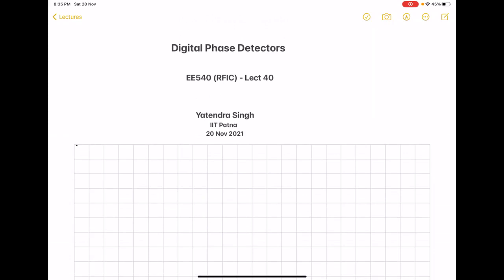In the previous lecture, we saw that analog phase detectors can be used, but unfortunately, they are capable of detecting the phase error only over a very narrow range. That too, the phase difference should be 90°. So it measures the slight deviation about the 90°. With the XOR gate, we found that they can also be used to detect the phase error, but they are capable of detecting the phase error up to pi degree.